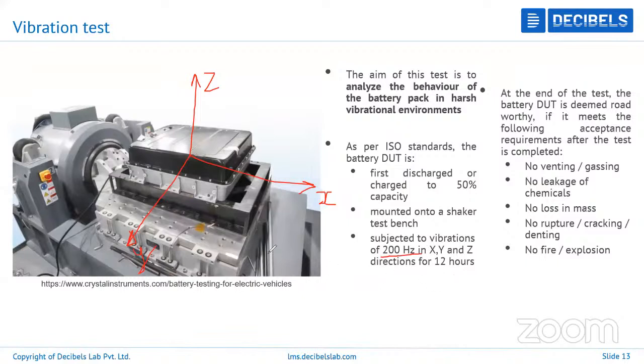Okay, so this is specific to the battery pack. It is not something that only one cell will undergo. The entire battery pack will undergo it, and it will be subject to a minimum of 12 hours. The reason is that the ISO standards dictate that a minimum of 12 hours is needed in order to sufficiently understand the effect of vibration on the chemicals present inside the cell, inside the battery pack.